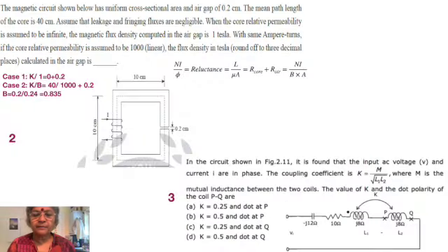Okay, so moving on to the third problem. Here we see some capacitive reactance, a resistance, and two inductances connected together in series with a dotted terminal and a mutual inductance between them. A dotted terminal refers to the fact that if current enters the dotted terminal in both the coils, then you are having aided fluxing, aiding of the fluxes. Otherwise, it's going to be opposing. So we have here such a situation, and let's read the problem.